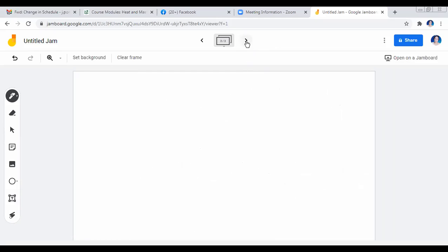So if we do that, the T for the second condition will be, now I will have the 1 over MA factored. So you will have 1 over MA. For the first term, you will have your initial moisture content minus the critical moisture content, and the denominator, which is your critical moisture content minus the equilibrium moisture content, which is 0.05.